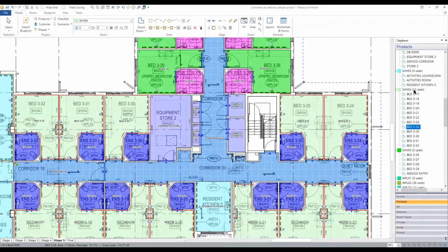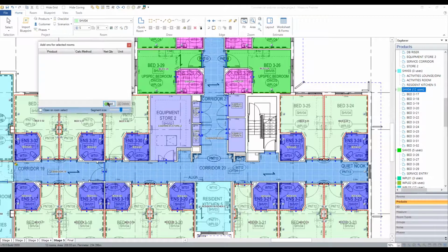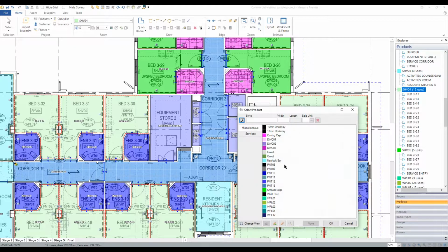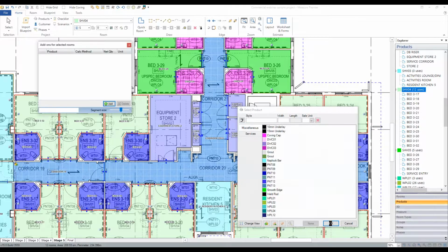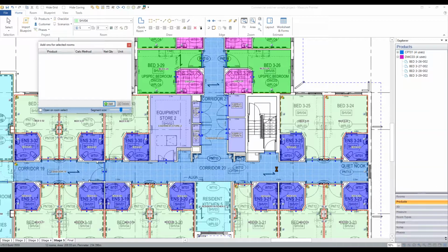So let's click on all those rooms. Then we could click on the add-on button, go down into add. We have a weld rod product somewhere. There it is, weld rod. So we'll do okay. So you can apply add-ons after the fact. It's just going to go through, figure out where all the joints are going, and therefore how much weld rod it needs.